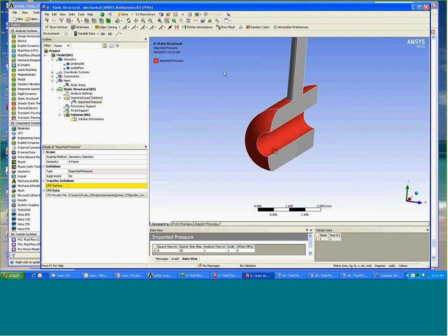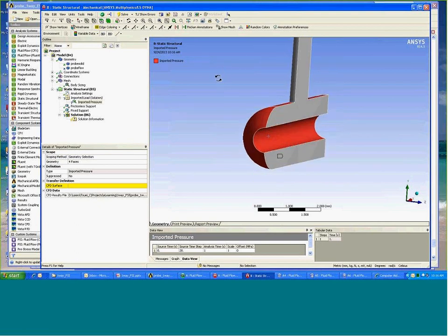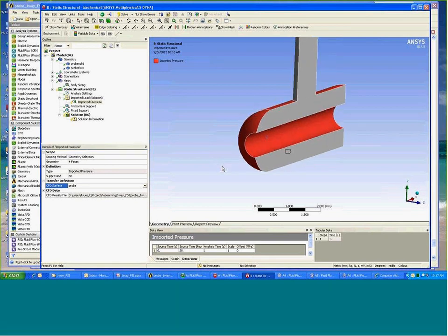which means I'm going to transfer fluid pressure from the CFD solution to Mechanical. And I select the matching surface right here from the CFD boundary condition. That is the reason why we need to define these surfaces and provide name selections for them in the CFD analysis, to make sure I can pick the corresponding boundary condition or fluid load from the CFD side, and I use that to transfer to the mechanical system.